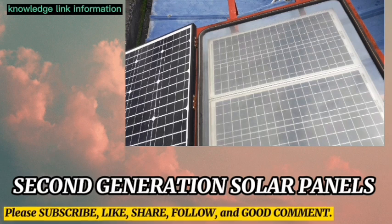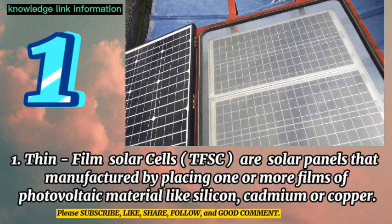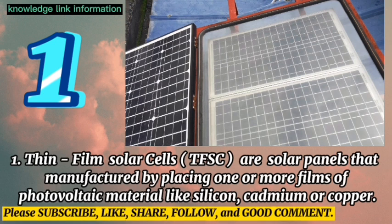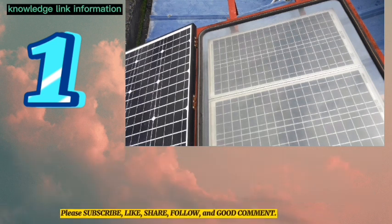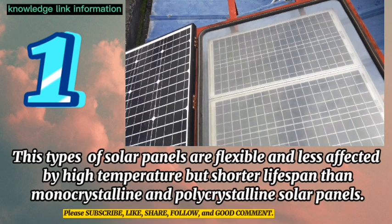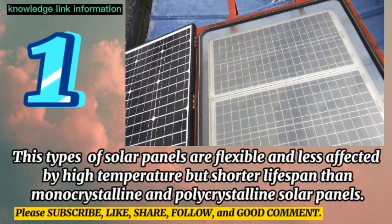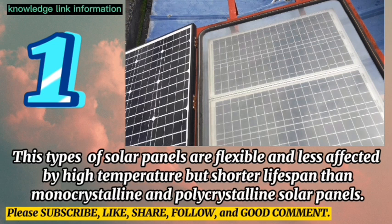Second generation solar panels. Number 1. Thin film solar cells, TFSC, are solar panels manufactured by placing one or more films of photovoltaic material like silicon, cadmium, or copper. These types of solar panels are flexible and less affected by high temperature but have a shorter lifespan than monocrystalline and polycrystalline solar panels.